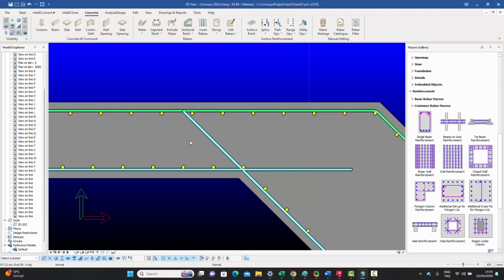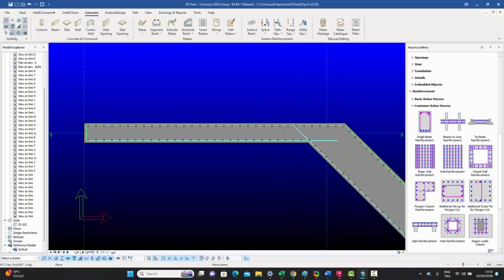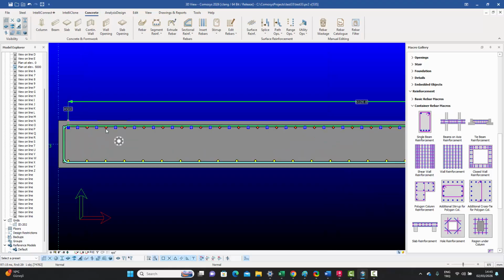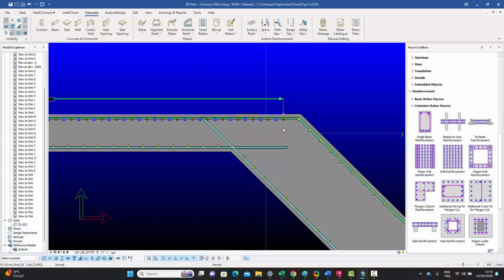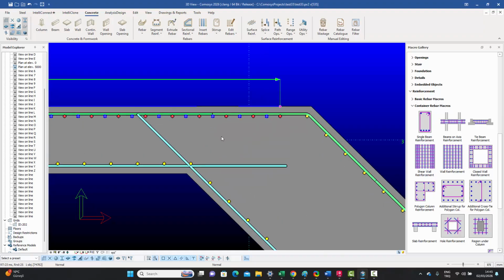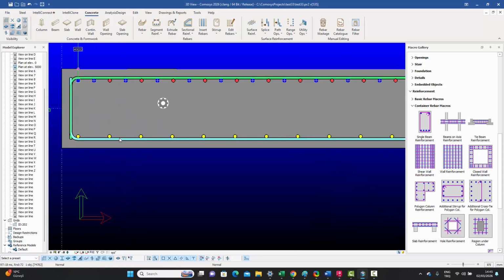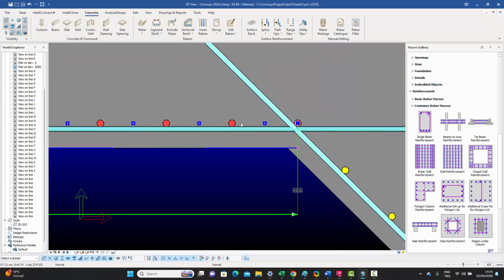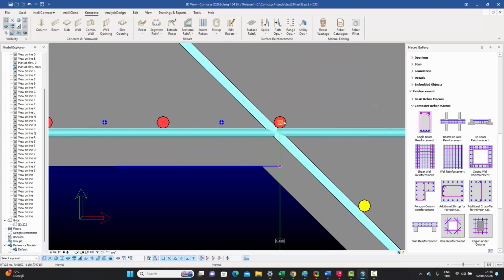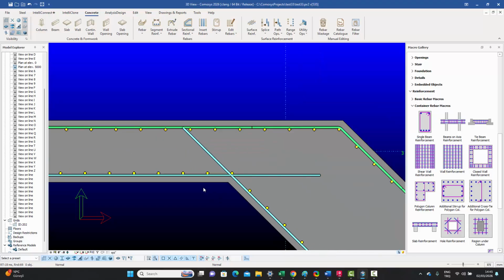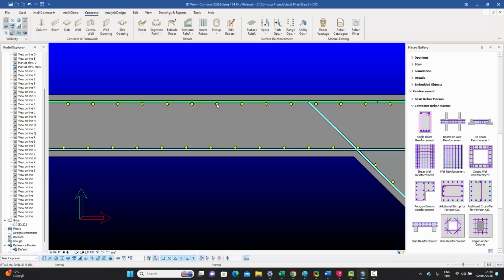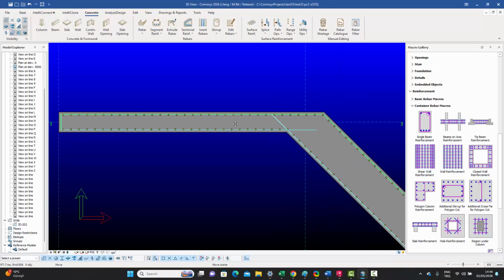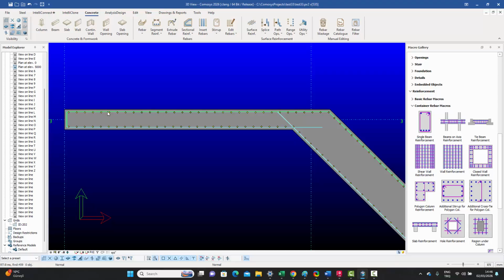And we note, there's one thing you can notice over here, because the side lengths are different. So this one over here is actually going all the way till the end, till over here somewhere, those bars. And it has automatically calculated the range for this bottom one over here, because this one kind of ends earlier. There's a bar at the corner over there as well, by the way. But there's one thing which you notice, that these bars obviously are not aligned. So this bar is not aligned, with a slight horizontal mismatch over there. And that's understandable because the lengths of the surfaces are different.